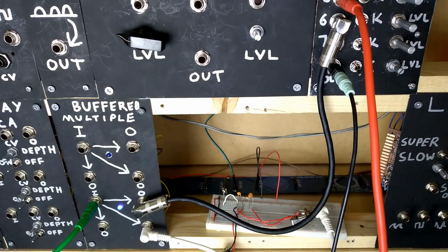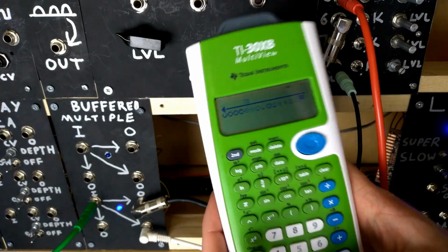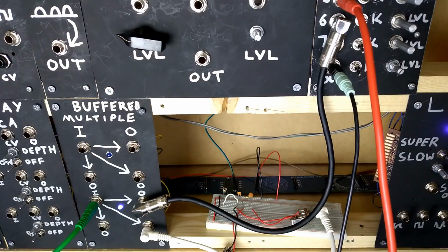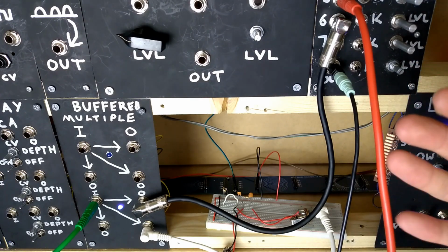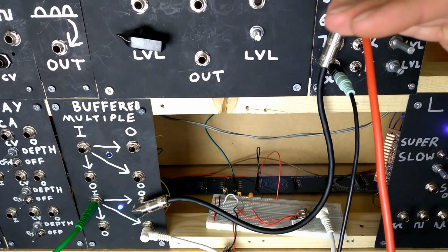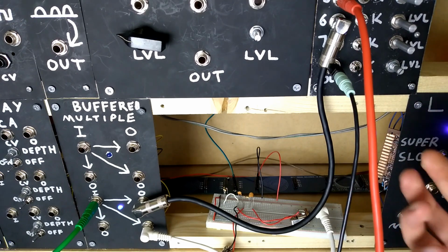So if we put these values into our formula, then we can see that our cutoff is around 1600 Hz, which is close to the cutoff of 2000 Hz like we had in our graph. I chose this value as it seemed like a bit of a Goldilocks number, not too low, but not too high, just enough to demonstrate how we can filter out certain frequencies within music.